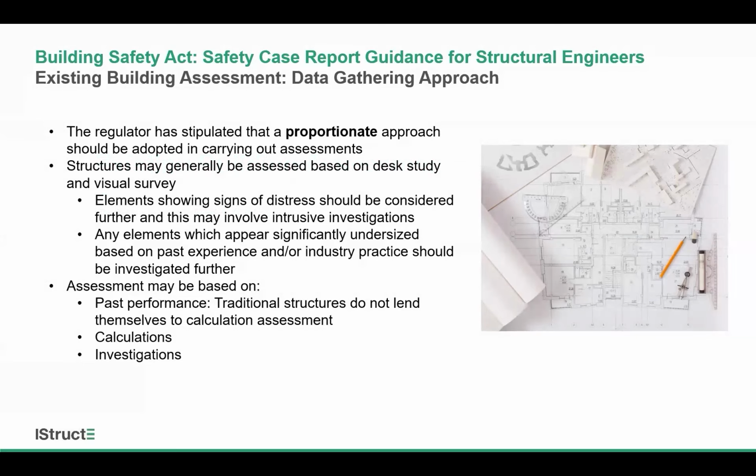effectively it's primarily a desktop and visual survey, at least initially. So it will be going through record drawings, doing site inspections to review the general form and layout of the building. Does it look sensible? Are the column grids appropriate? Are the stability elements in the right place? Do the member sizes look about right? There'll be an element of site inspection to look for any signs of distress or movement or anything that might prompt concern.